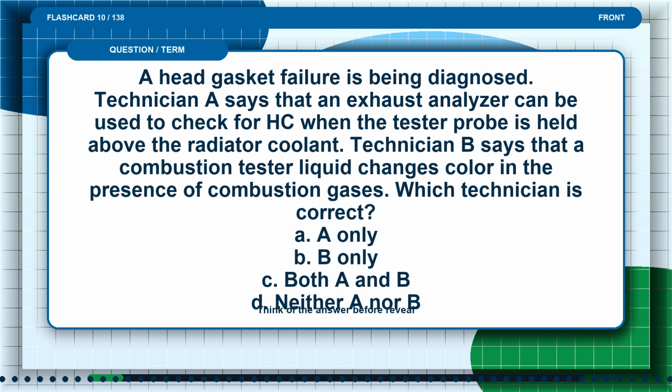Flashcard 10. A head gasket failure is being diagnosed. Technician A says that an exhaust analyzer can be used to check for HC when the tester probe is held above the radiator coolant. Technician B says that a combustion tester liquid changes color in the presence of combustion gases. Which technician is correct? A only. B only. C. Both A and B. D. Neither A nor B. Pause and think of the answer before the reveal.